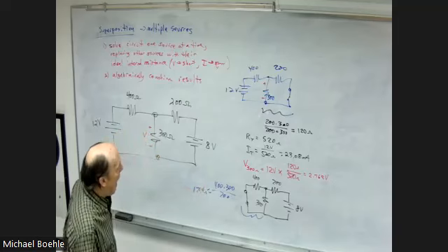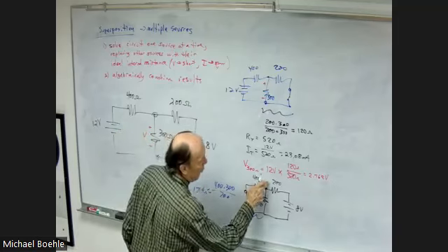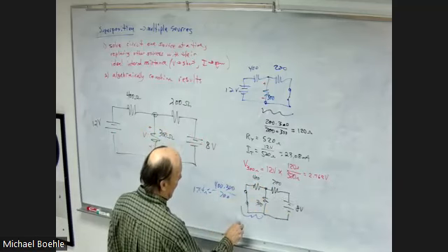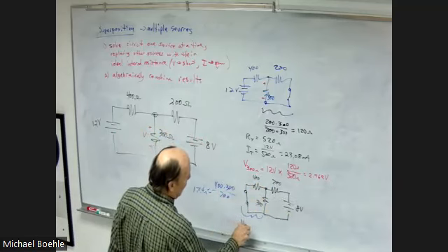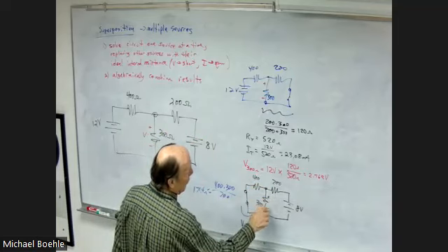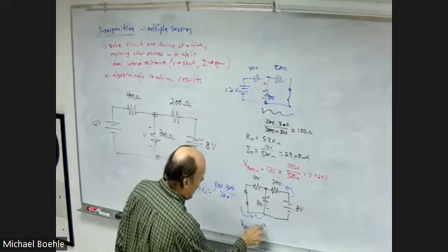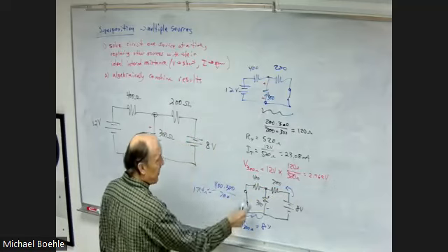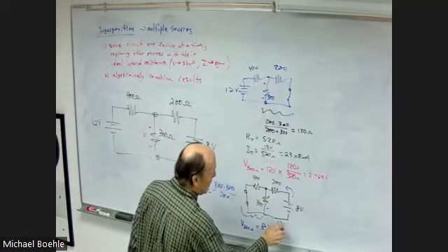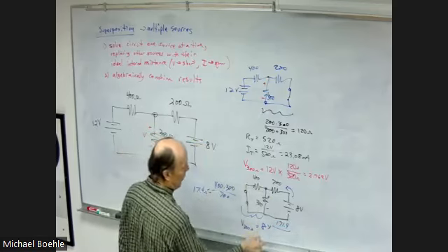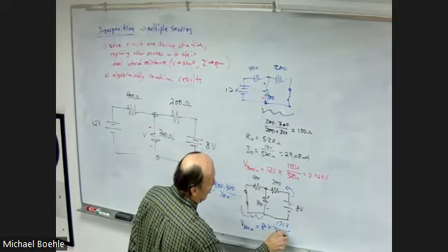Now, that will be in series with the 200 ohm resistor, and that will divide the 8 volts. So I can go ahead and skip ahead here. The voltage across the 300 ohm resistor, right? And notice this will be the polarity because that's my direction of current, will be 8 times 171.4 divided by the total resistance, which is 171.4 plus 200, so that's 371.4.